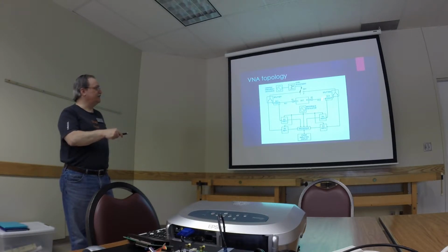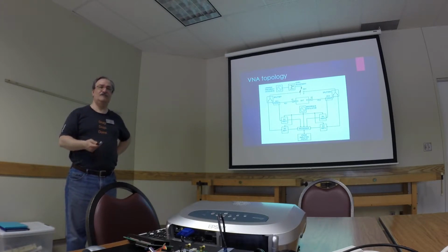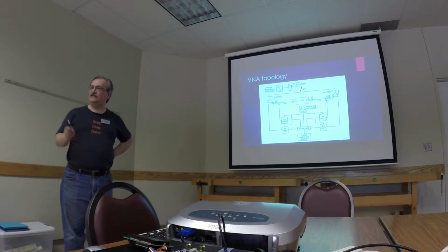couplers, two of those. The precision cable, which is PC1 and 2 here, is really only something that comes into play with cables like that manufactured by Megaphase. I was saying at the break, the shortest ones I know of are about a foot, but they're metric in length, and they run about $150 a piece new.